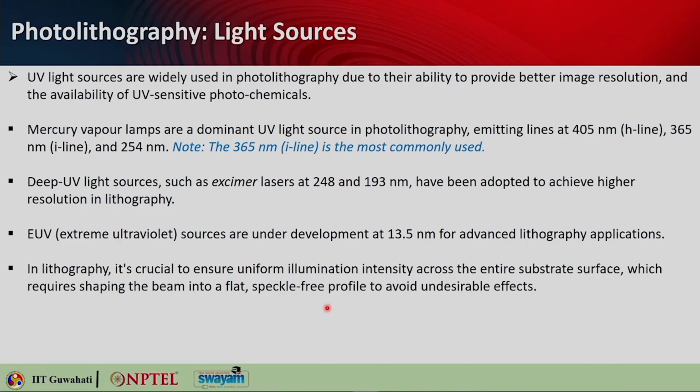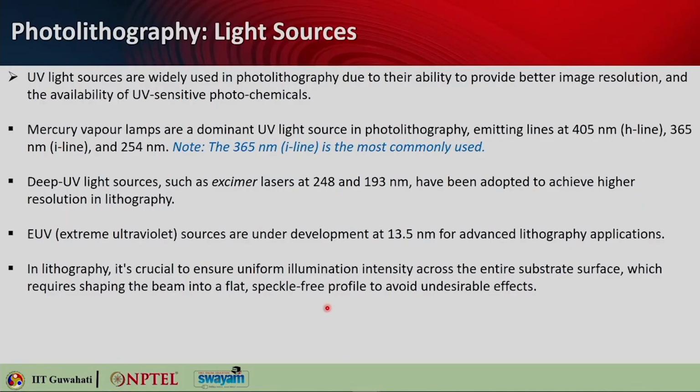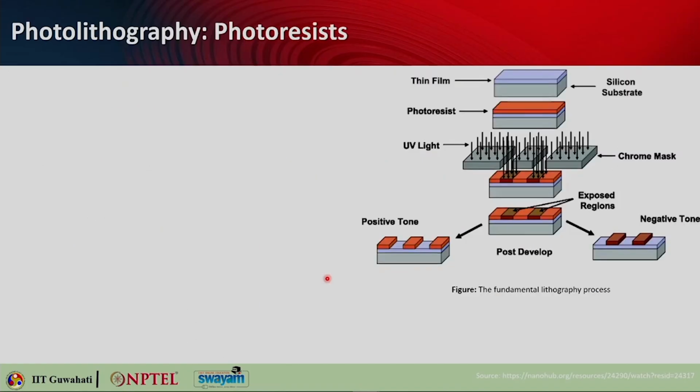When you think of speckles in a lithographic pattern, they can degrade the quality and the precision of the final image, especially in applications where you aim for high resolution, such as in semiconductor manufacturing. So, in those cases you need to make sure that uniform illumination intensity is available across the entire substrate's surface. So, this is typically the process of lithography.